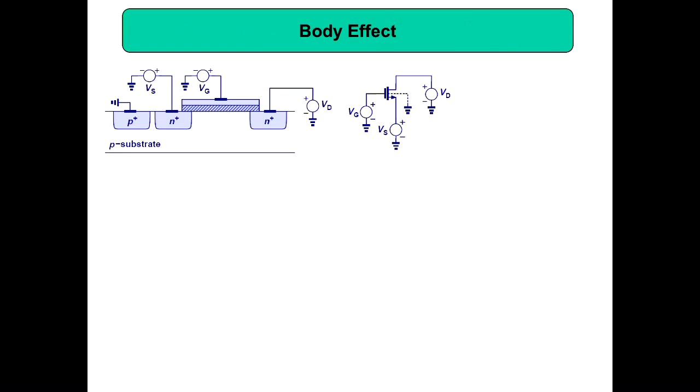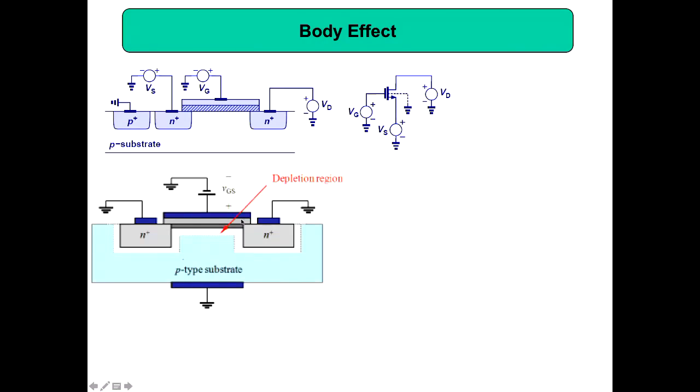Then sometimes people write, in this one we don't have to study body effect, but still I thought I will use this slide, because sometimes you will see people write MOS and then they put a ground from here, you might have seen. What is that symbol? Most of the realistic circuits, they put from here a dotted symbol to the ground. Sometimes they connect some voltage here. You should not get confused, because you studied MOS transistors, PMOS, NMOS, but then you see some new notation and you might be thinking what these guys are doing. What they are doing is they will ground the substrate sometimes. So that's what is shown.